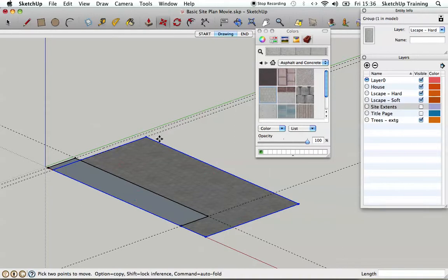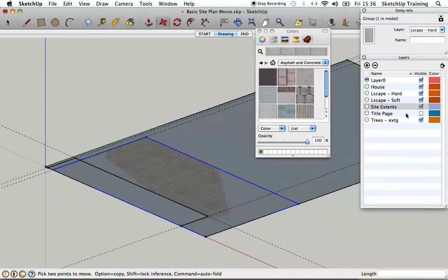and you can use that procedure to continue tracing around, putting in guidelines where you need them, and drawing in the objects, either using the rectangle tools, adding them and subtracting them, or just tracing using the line tool around your guides and using a combination of that and measure type dimensions. But the other thing we're going to do is show you how we can add some dimensions and text to that.